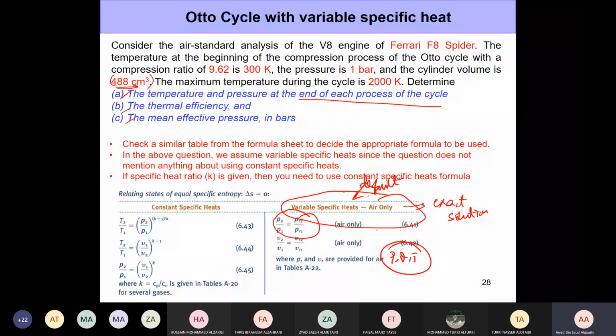But the key part is to know that you're going to make use of this, all right? And of course, another thing to remember is this applies only when you're dealing with isentropic processes. You can make use of it during the compression or the expansion process, which are both isentropic. You certainly cannot use this formula to relate the pressure ratios when you're looking at the heat addition or heat rejection processes. That simply is not correct.